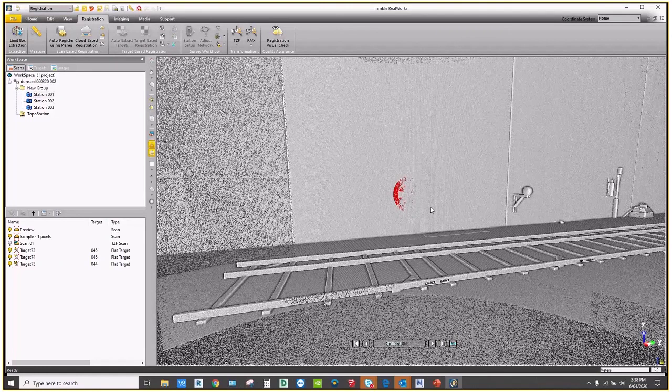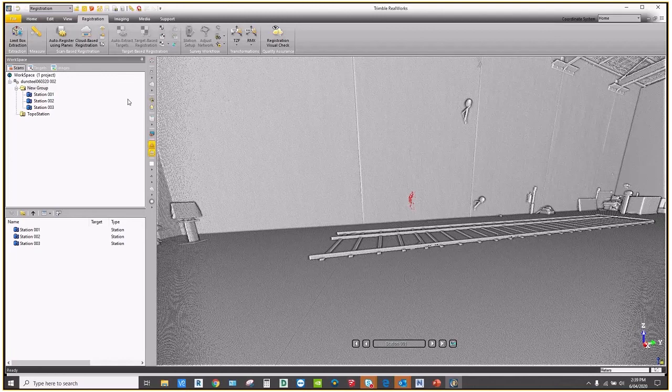Okay. As I said, the beauty of using this method is that you've got more control over what's going on there. Depending on the accuracy of the results you're looking for, you can decide what residuals you're going to accept and what you're not going to use. Whereas in the automated way, it has tolerances that it won't process outside of. So in here, you've got total hands-on control about what you're using and what accuracy you're happy with.